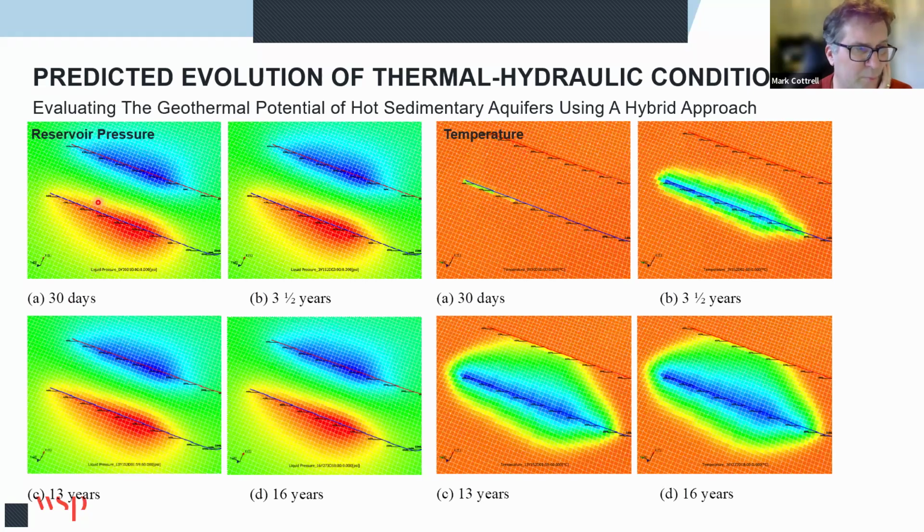So we need to be conscious that the injection pressures do not cause us any issues in terms of containment. So things like caprock leakage, interaction with faults, all require us to understand, well, how does the reservoir pressure evolve during that injection and production process.